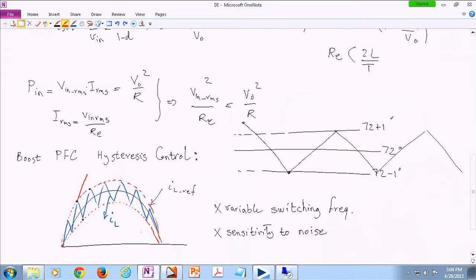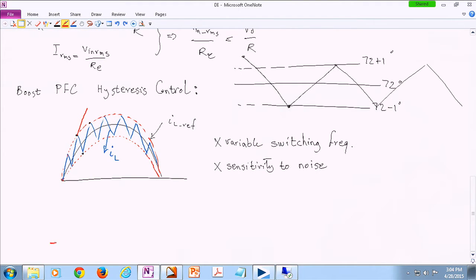Okay, so for instance, your inductor current has a DC component, and then you consider the fundamental harmonic. You actually approximate this with some fundamental harmonic, and you consider both harmonics. So you have like a two-dimensional kind of a model. So you have four transfer functions basically. There are lots of papers out there using this technique, especially for PFCs, because you have a significant 120 hertz ripple everywhere basically. So there are some papers out there.